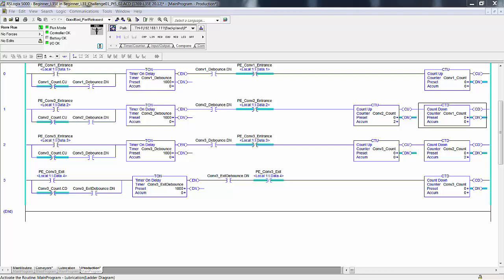Then there's weighted buffer, a modification of that. Conveyor 1 passes through to conveyor 2, which buffers cartons, or conveyor 1 can buffer and then pass through conveyor 2. So that gives you 3 options with those 2 conveyors. Both pass through, one buffer, well, actually 4. 2 conveyors pass through, 1 pass through, 2 buffer, 1 buffer, 2 pass through, or both of them buffer. Those are most of the limits to what you can do with sensors and non-reversing motors given in this application.